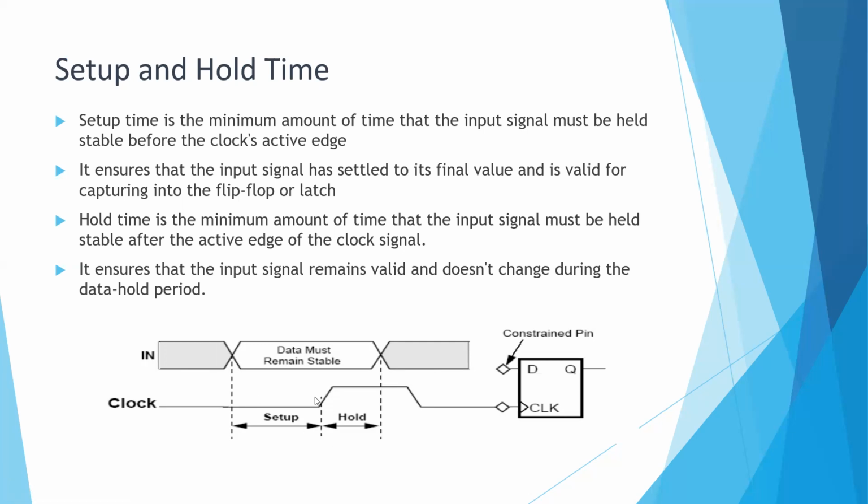Suppose you are applying a clock. Before the clock's active edge, your data must remain stable for a certain duration of time. This is called the setup time.